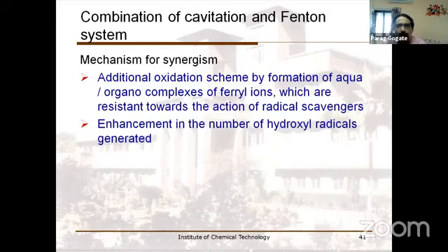I can also think of combining cavitation with Fenton. In Fenton, again, you are having hydroxyl radical formation, but typically what you get is that sometimes you are going to generate complexes which can be broken down by hydrodynamic cavitation. So in this sense, you will get an enhancement in the number of hydroxyl radicals which are generated.